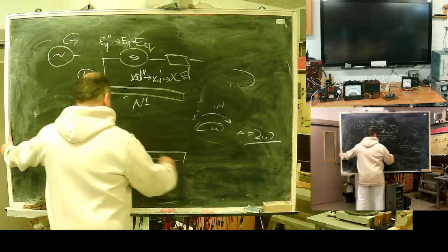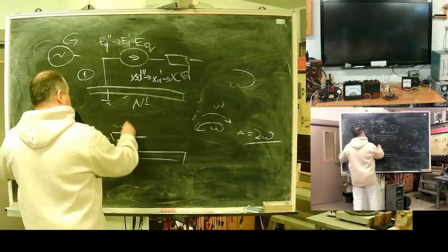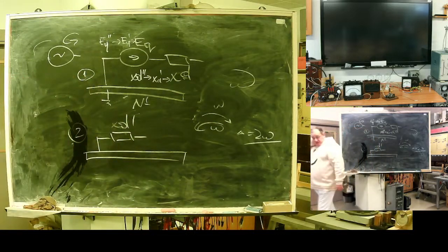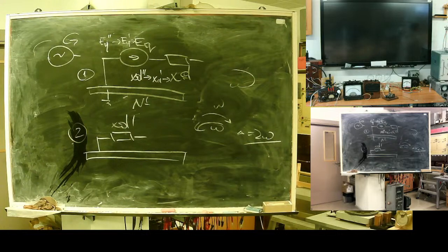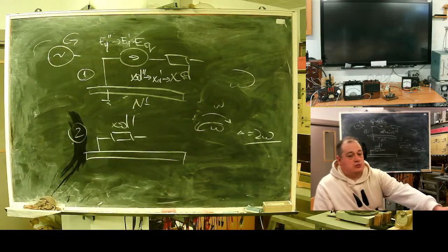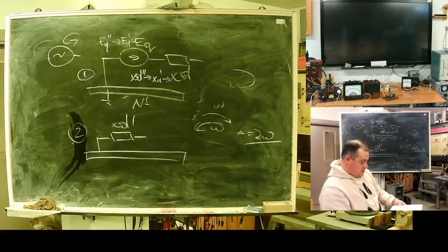As reactance for negative sequence, approximate transient reactance should be accounted, but again, take time to look into the manufacturer's data. Usually, manufacturers do supply you with this number.